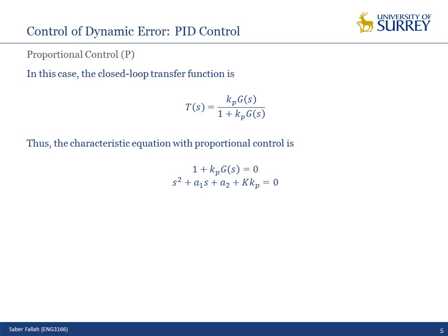It's not acceptable. If the overshoot is important for me, Kp alone is not working. The proportional controller is a good controller as long as our expectation from the controller is limited. You can improve the damping with the proportional controller only by a limited value.